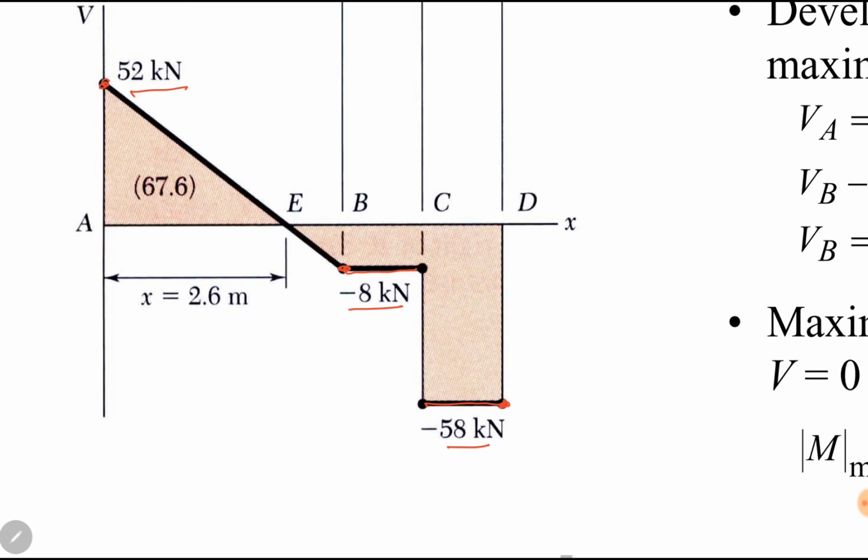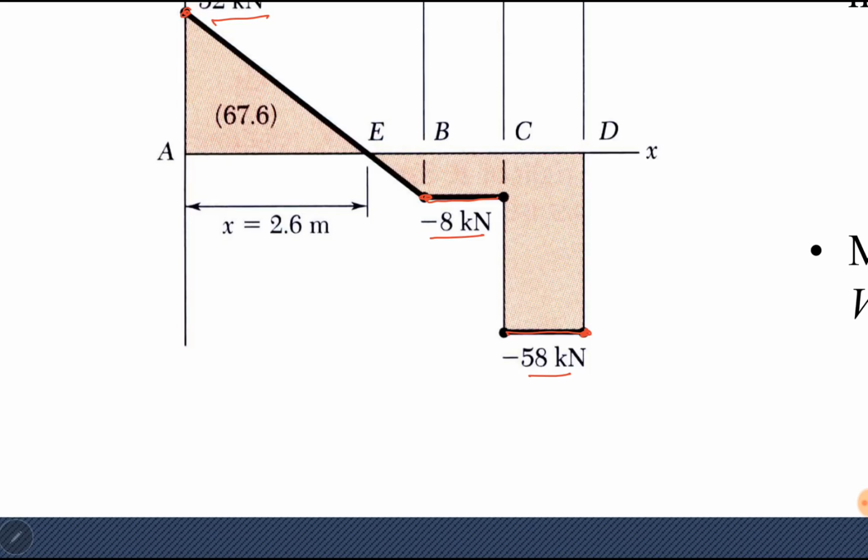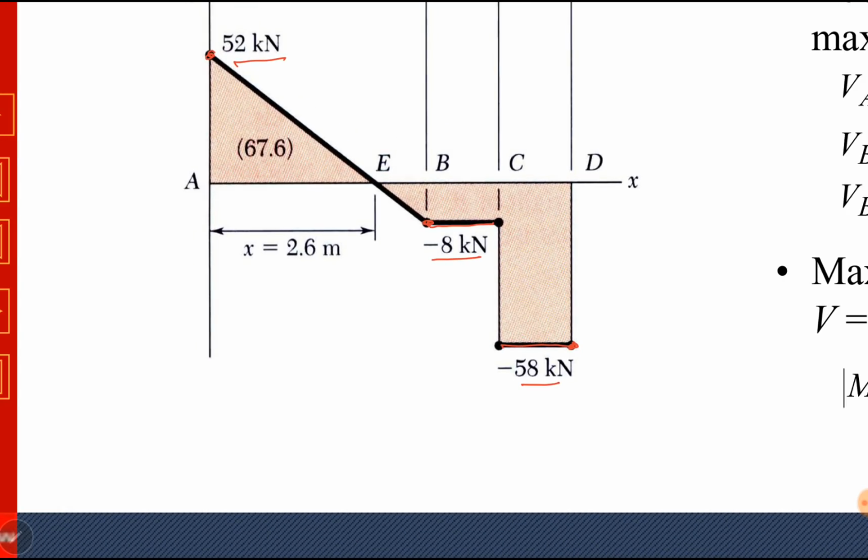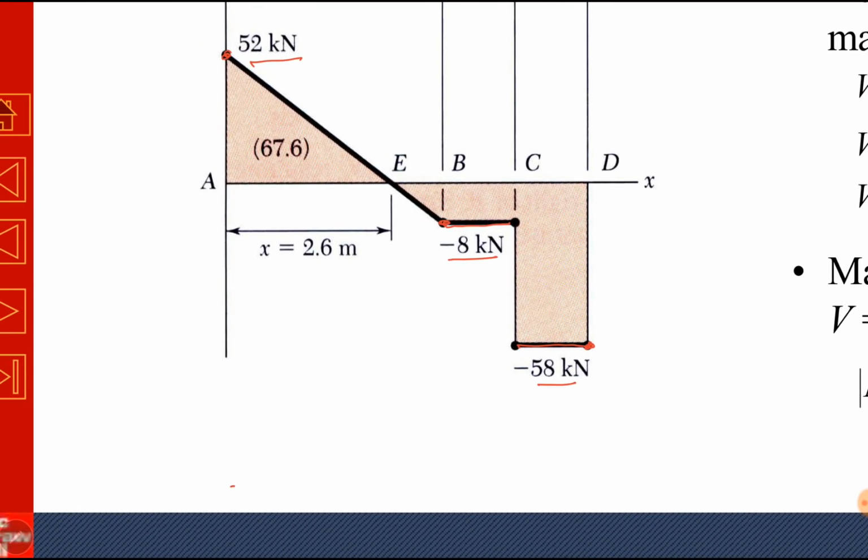Okay. We have drawn a shear force diagram, but actually we need the maximum bending moment. Either we have to draw a bending moment diagram, or we can find the maximum bending moment from the shear force diagram as well. Before that, I will draw a bending moment diagram, and then we can discuss another method of how to find the maximum moment from the above diagram. Bending moment in kilonewton meters.